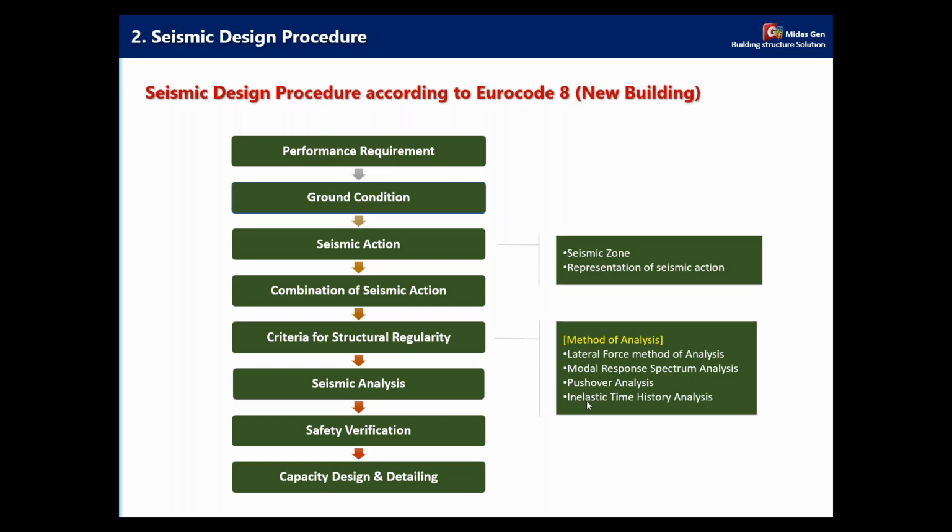For the pushover and inelastic time history analysis, because they are non-linear, we are going to focus on the elastic system using these two methods: the lateral force method of analysis and the response spectrum analysis. We are going to compare the two methods, and you are going to realize that the response spectrum analysis is the best compared to the lateral force method analysis.